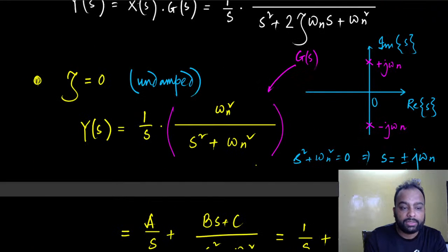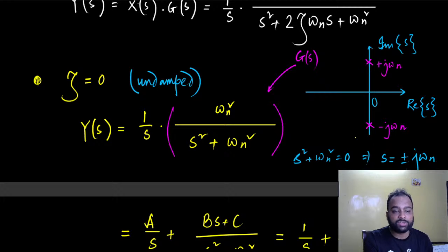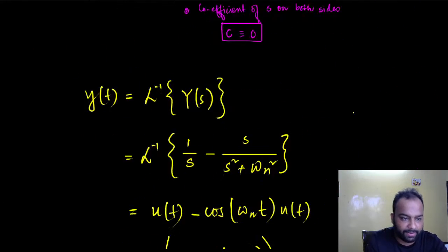This was the undamped system, and for this undamped system, the poles were on the j omega axis, and the distance of the poles from the origin denoted the undamped natural frequency. So omega n has this value, the direct distance here.